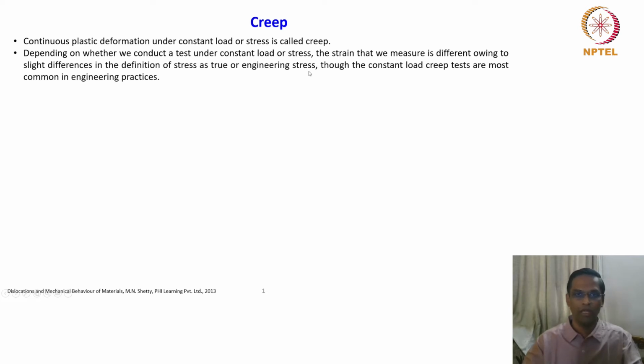This we know, why we call it true stress and engineering stress. We have already seen this. Though the constant load creep tests are most common in engineering practice, we are going to talk mostly about the constant load creep test. Of course, we can do a constant stress creep test, that requires some special setup in the machine. But most of the testing machines conventionally used in the lab are constant load creep testing machines.